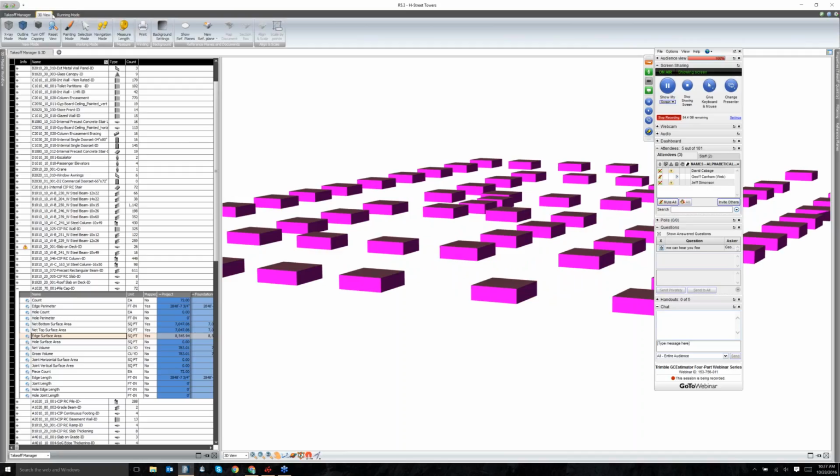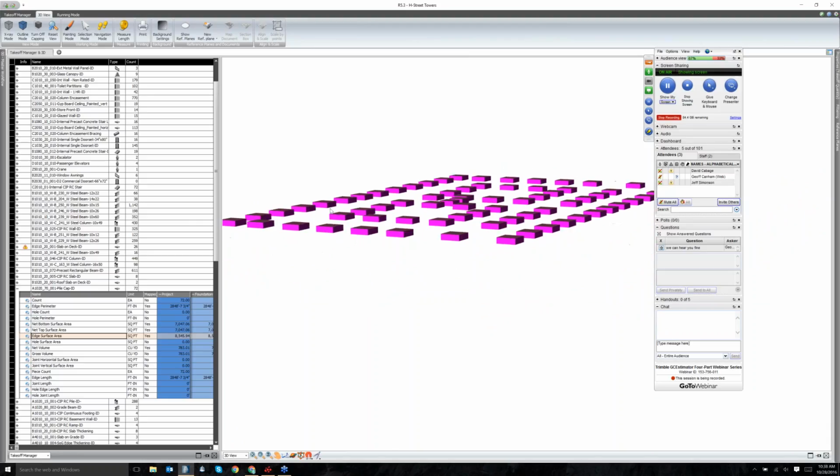To give you a bit more confidence in your model, we give you a measuring tool so you can snap to a corner and see that this particular column is 9 foot 11 3/4. So quick analyzation, quick understanding, and we give you the ability to do manual takeoff as well. Instead of clicking on four corners, you can just click a face and understand what it is and derive all these what we call construction caliber quantities.